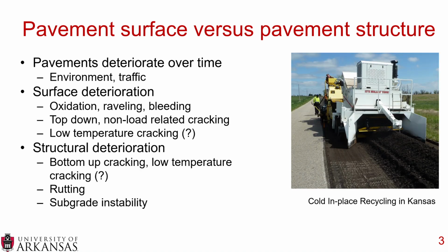But certainly for structural deterioration, there's bottom-up cracking. Again, I list low temperature cracking here with the question mark. If I ever see you at a conference, I'd be happy to talk about whether or not low temperature cracking is surface or structural, because I don't know. I could say either one. But certainly other structural deteriorations include rutting and subgrade instability.